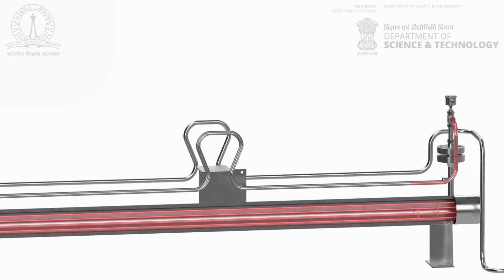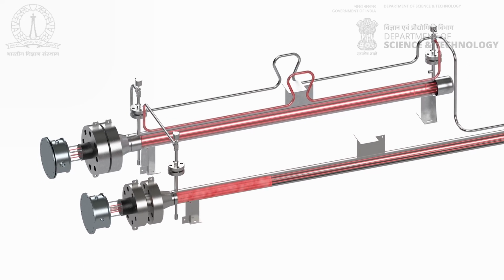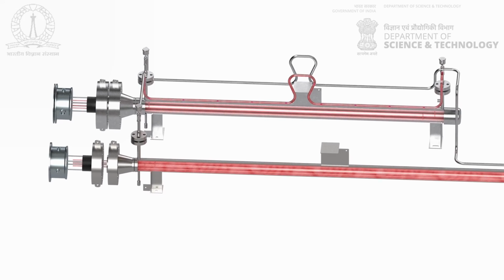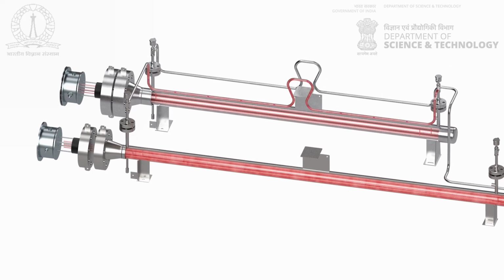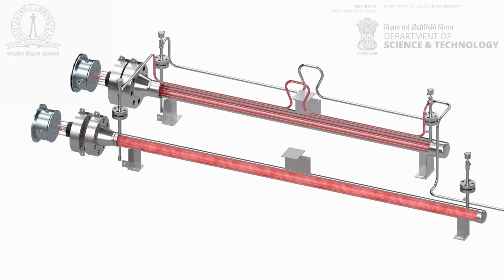The second stage heater is a stand-in for the external heat source in an actual installation, which could be concentrated solar heat from a solar tower, a coal-fired boiler, or exhaust heat from a gas turbine in the case of a waste heat recovery system. The combined heat addition from both stages is about 141 kilowatts.